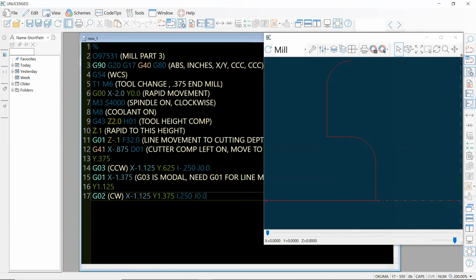I've pulled up my plot viewer, which is going to help me see the geometry as I am putting down each line. This is a very helpful tool that Discriminator gives. Going line by line, you can see the point movements of your cutting tool. While this may not show cutter compensation errors like the simulator does, it at least can give confirmation that your geometry is correct.